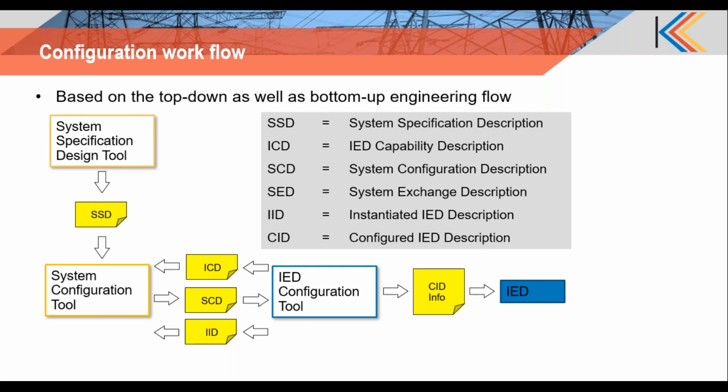Now let us see what is SED, the System Exchange Description. I was telling you 61850 is no more limited to a single substation, and it's possible that you can have multiple substations that are exchanging information. Also, it's possible that we can have multiple defined boundaries within the substation, which are managed and maintained by separate SAS functionality or SAS projects. So in that case, we have the concept of a project where some of the IEDs in one substation are owned by one particular project, and there is another project which owns some other IEDs. So these projects can be referring to two substations itself.